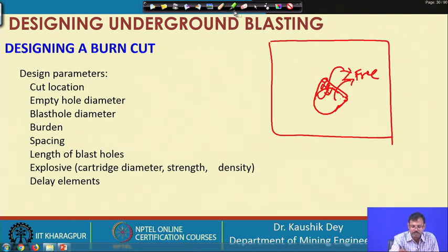So, this is the basic idea of this blasting. Before the next blasting, this is the total free area available. Like that, we are gradually increasing the free area or opening area, so that it can act as the free face for the next hole, and in this way we reach the desired advance or desired pull.